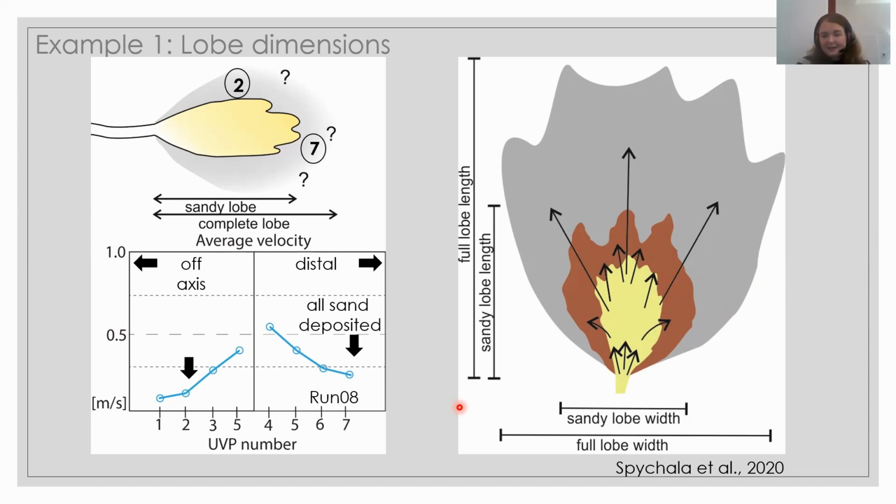And this is not actually that surprising, because in this 3D flume, what always happens with the silt material that we put in is that it would have traveled way further than the dimensions of our flume, and it in turn gets reflected. So it cannot quite travel freely. But you can do a very quick calculation on how long the flume would have to be for them to freely settle out of the flume. You would have to have at least 20 meters of length for them to settle and not be reflected at the frontal flume walls.